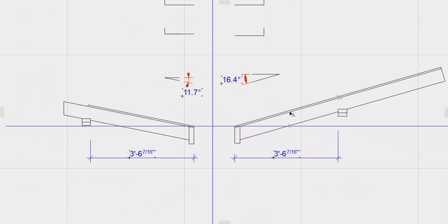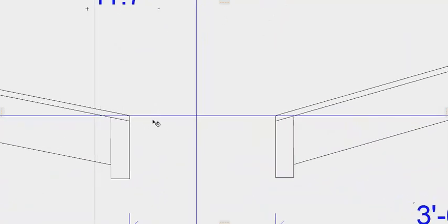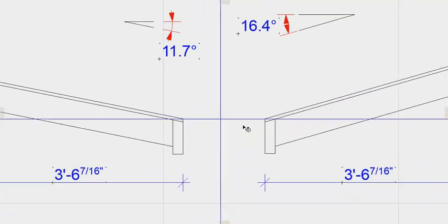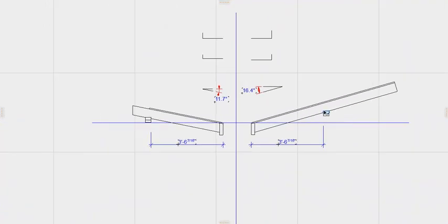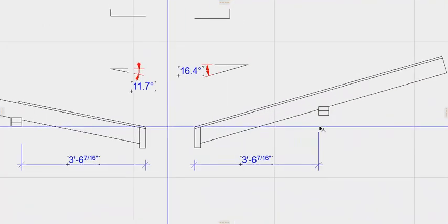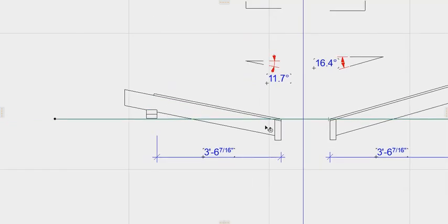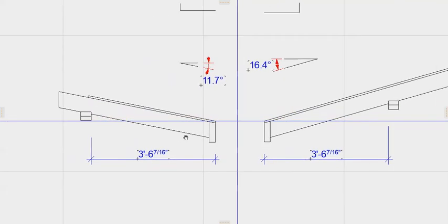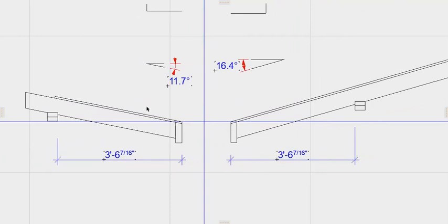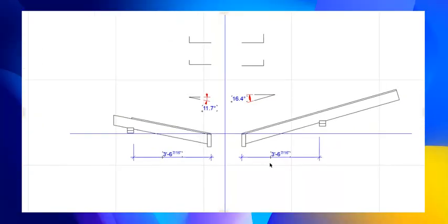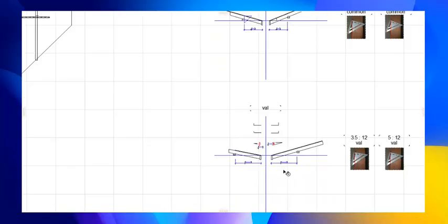You offset the 5/8 for the plywood, you offset for your rafter, and again, you want these to be on the same line, so you can tell the difference in the top of your wall. You measure that down to your same parallel line there, and then you know what that is. So that's a little mock-up for how to do the 2 different valley rafters. You can look at the previous video for the other annoyances that show up as part of trying to meet these kinds of weird scenarios in a valley.